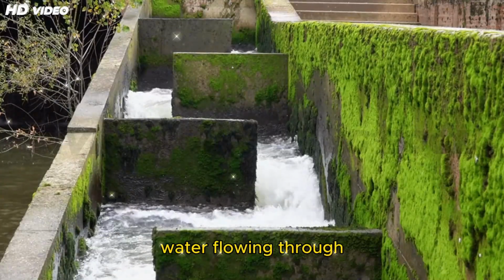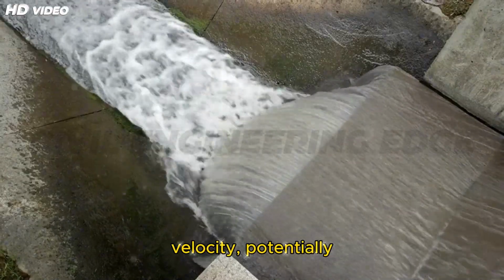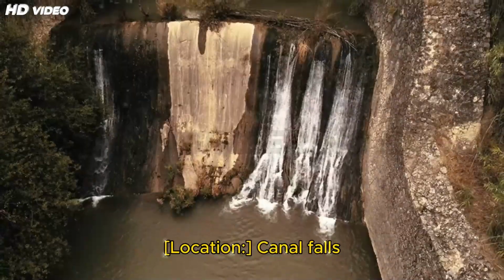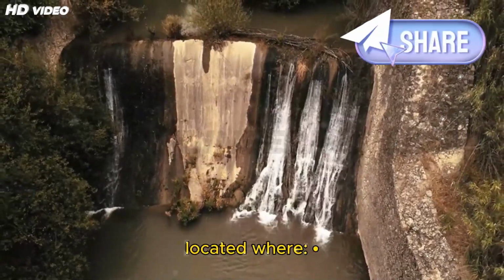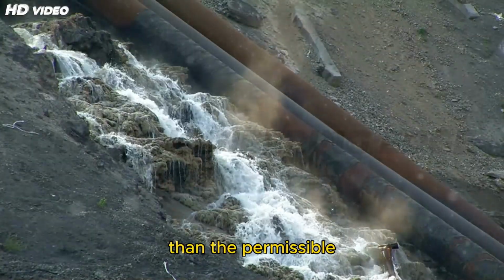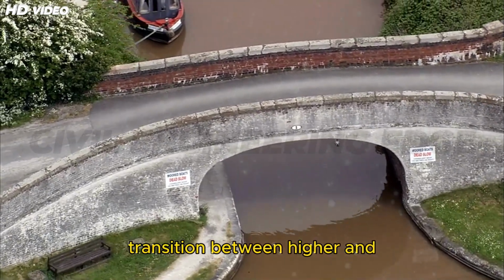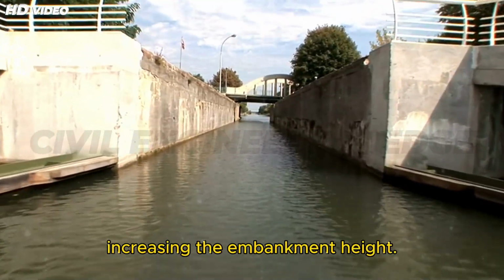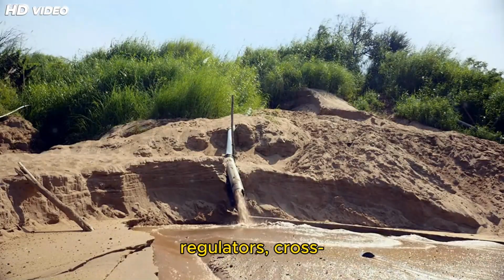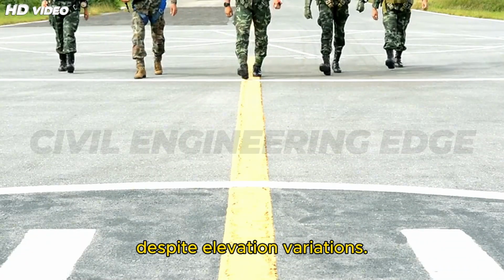Without canal falls, water flowing through steep stretches would gain destructive velocity, potentially causing scour, embankment failure, or excessive sediment transport. Location: canal falls are strategically located where the natural slope of the ground is steeper than the permissible bed slope of the canal. There's a requirement to transition between higher and lower reaches of the canal without increasing the embankment height. Near structures like head regulators, cross-drainage works, or branch canals, command areas need uniform supply despite elevation variation.